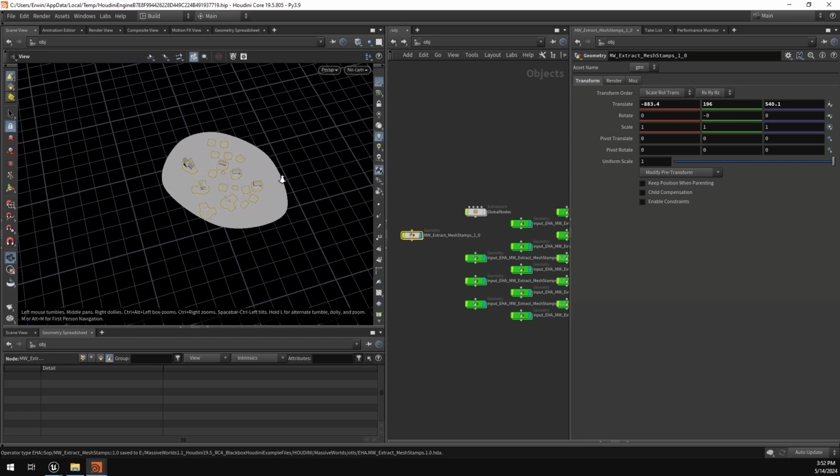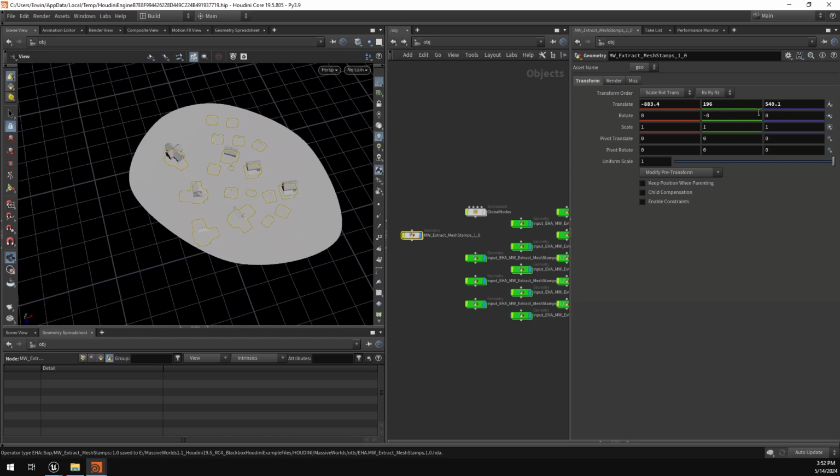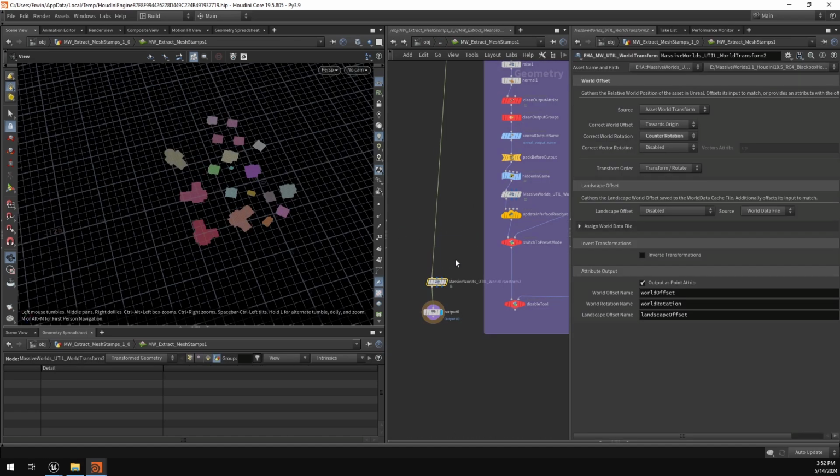So even if I go ahead now and give a rotation in, let's say the Y rotation, because that's ultimately how Houdini reads its up vector, it doesn't actually move, right? Nothing changes. And that's intentional, because this node undoes that particular transformation.